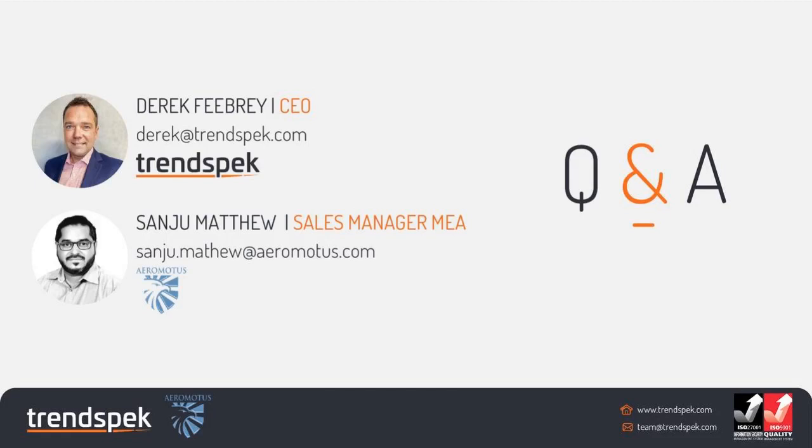Yeah. And they deliver such good models using the RTK because the positioning of each photo as it goes through reconstruction makes really good models which are really, really accurate, especially internally. But we've got a new ability to do thermal modeling, so to also harness that H20T, and it works in the exact same way. So you'd be able to switch between the visual model on the left and the thermal model on the right, or if you're just looking at the thermal model, you have the same functionality, so you can right-click on it to bring up the original thermal image that went in to build that model as well.